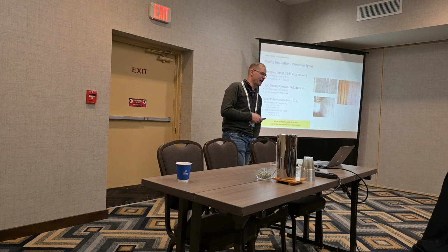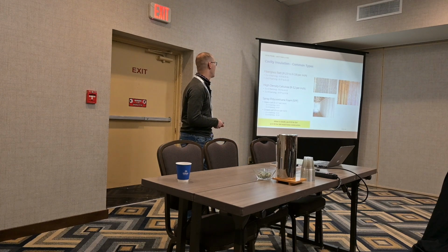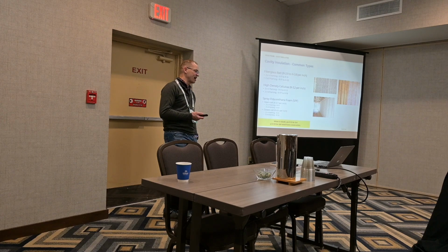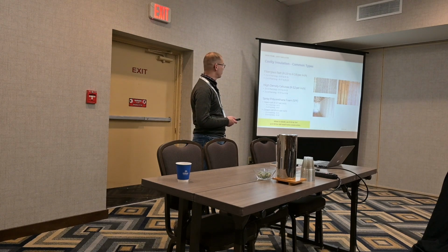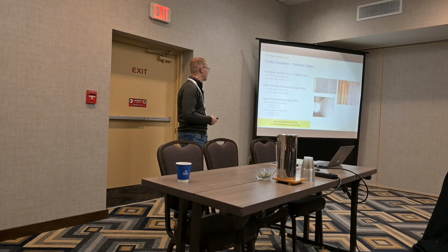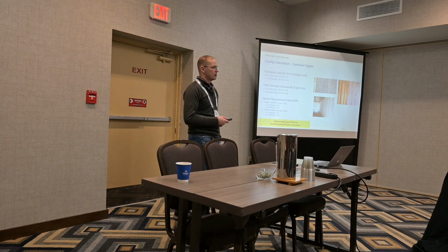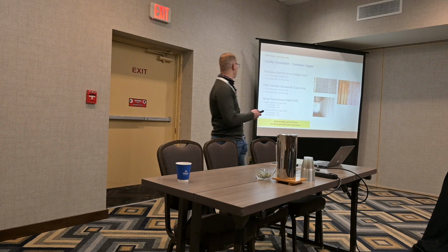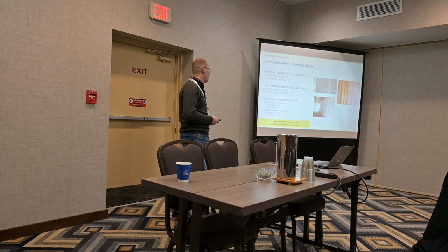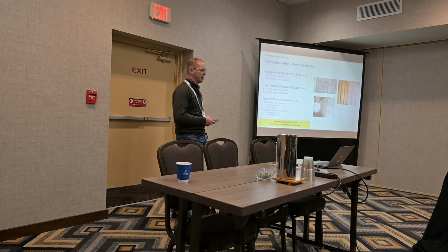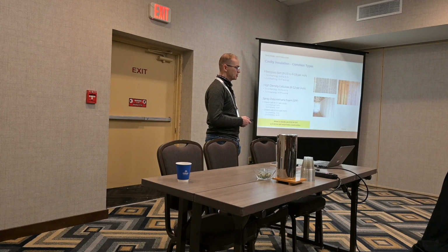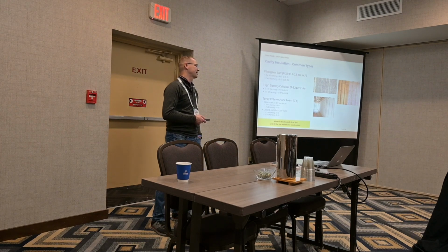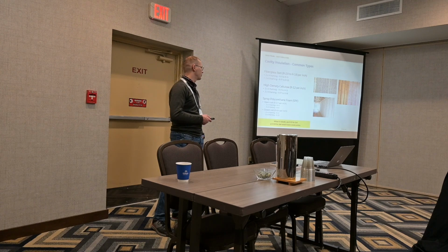All right, so cavity insulation, common types. There is a lot of insulation. There's fiberglass batt, that's traditional. It's still used a lot today. High density cellulose gets better with R-values of 3.2 per inch and continues to improve. Spray foam, polyurethane foam is even better. They can even get 3.7 and all the way up to 6.0 for an R-value on those.